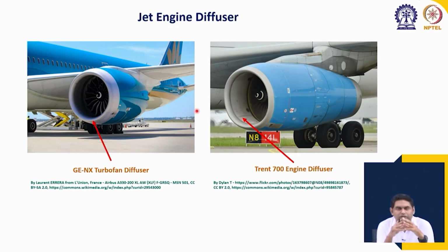Anyway, for normal aircraft there is a section which is known as the diffuser. You can see this front section before the fan blade. Here this acts opposite to a nozzle. Okay. Here the cross sectional area gradually changes such that the flow velocity decreases. Okay. Flow velocity decreases, and as a result the pressure increases. So, you will need less pressure from the compressor.